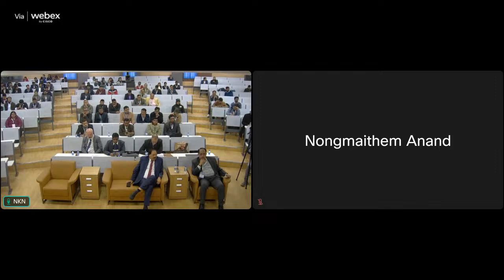Now what I have done is that I have taken 4 classes of rock here. One, the poor rock, represented by Q from 1 to 4. Second one is fair rock, represented by Q 4 to 10. Third is good rock, represented by Q value 10 to 40. Because I have limited time, I have confined my study from Q 1 to 40.